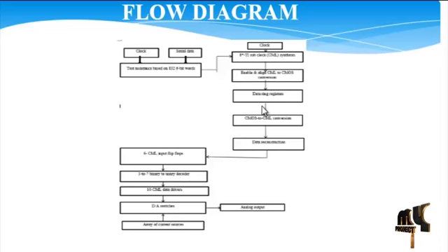The output from an ideal DAC has a zero order hold output, and the black sinusoid is the original ideal analog signal that has been digitalized and fed to the DAC input. The blue stair step pattern is the ideal output from the DAC. This is one of the first 28 nanometer DAC implementations and the first high speed 1 volt only design.